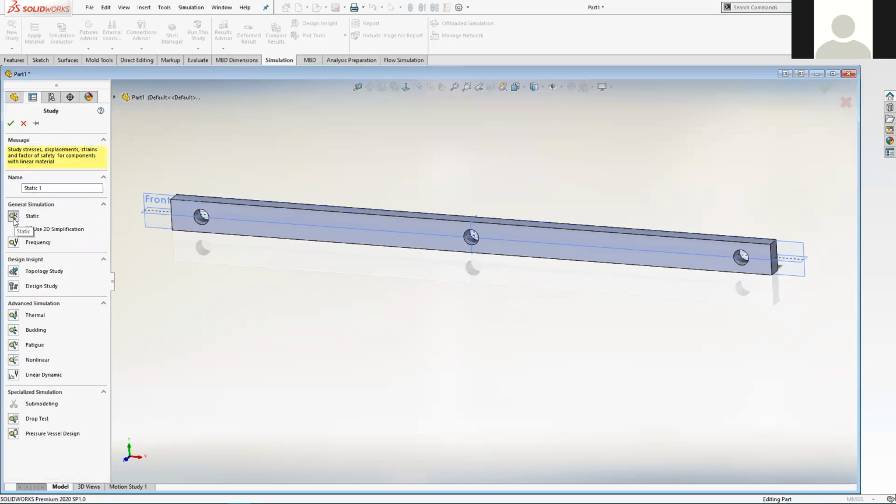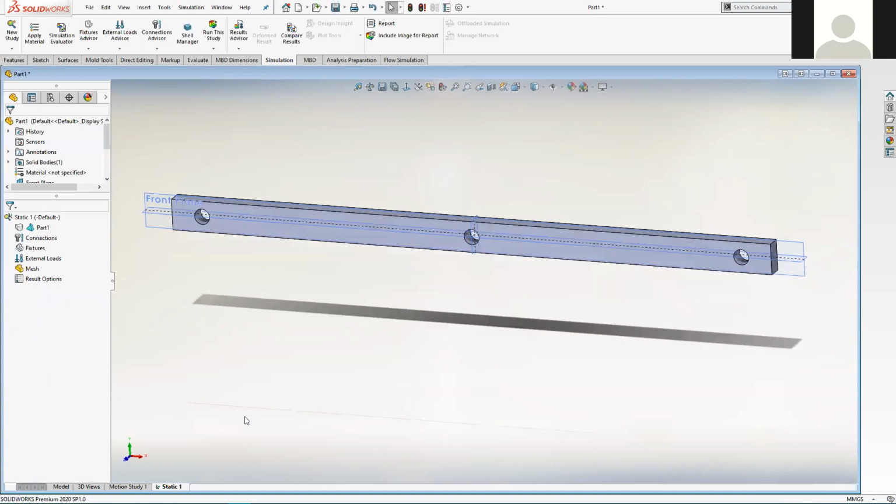And then again, we're just using almost the most basic study that you can set up in SolidWorks, the static here. We're not going to dip much into the other types, certainly not in this module. So leave it on the default static, click on OK, and then again, we're just going to run down the icons here from the top to the bottom, addressing the ones that need addressing and doing the setup in the ones that need that setup.